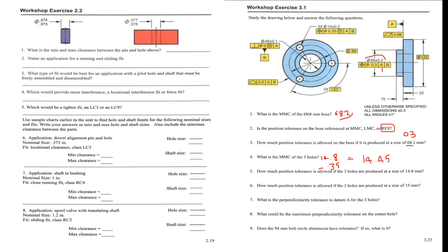14.45 is the MMC of those three holes, and the position tolerance if the three holes are at 14.8 would be 0.35. Then next, here is how much position tolerance is allowed if the three holes are produced at a size of 15. Okay, so it would be 0.55,